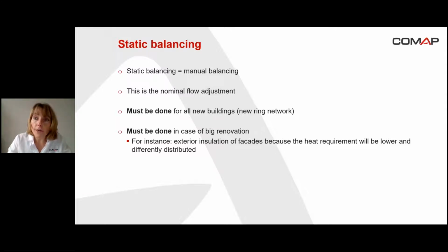in the year. For example, in Briançon, in France, in January, the outside temperature may be minus 19 degrees, and so the nominal flow is calculated in order to heat the room when the temperature is as low as minus 19 degrees outside. So that's the maximum flow we can have through the emitter.